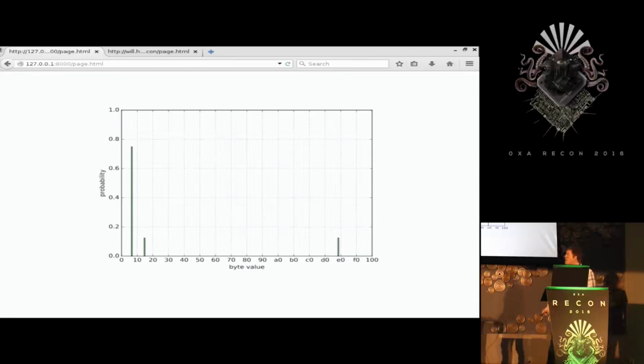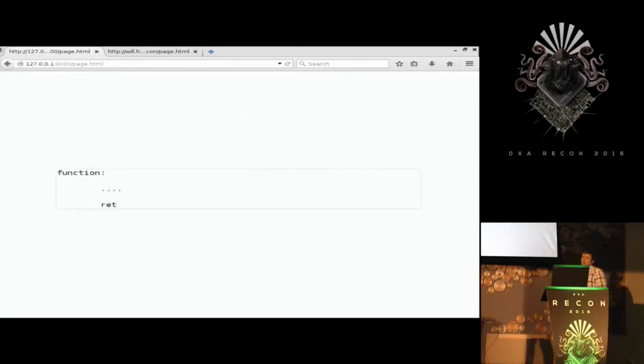But there's other function structure that we can use to our advantage. Functions generally need to save and restore callee saved state. And some embedded arcs save it for you, but most are pretty simple. And this is where, on this particular target, I stopped being able to use fancy histograms and analyses, because the sample size is just too small. Everything just gets lost in the noise floor, and there's no point in looking anymore.